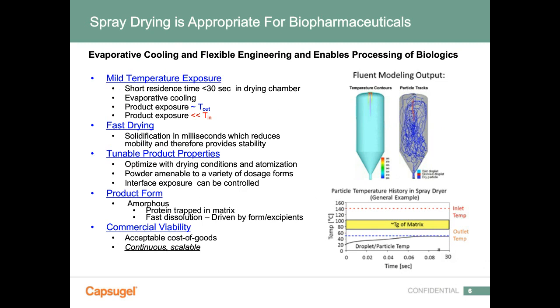I wanted to start off by talking about why spray drying is appropriate for biopharmaceuticals. There's a reason for this, and it's based on the fact that we're utilizing an evaporative cooling step. You're processing a material from the liquid form, and it heats up to the evaporation point within the spray dryer. Again, the wet bulb temperature of water is around 40 degrees Celsius. The drying temperatures allow for a mild exposure with a really short residence time.